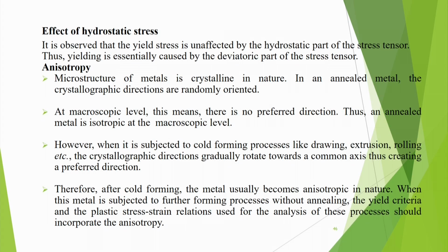It has been observed that the hydrostatic part of the stress tensor does not cause any yielding. It is only causing maybe some volume change, some elastic deformation, but it is not causing plastic deformation, and essentially the yielding is caused by the deviatoric part of the stress tensor. A lot of experiments have been done. Suppose we take a solid ball or solid object and submerge it deep under water, where there is a lot of hydrostatic pressure, and from all sides the pressure is equal.